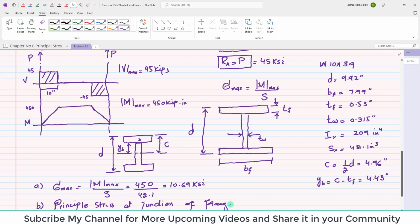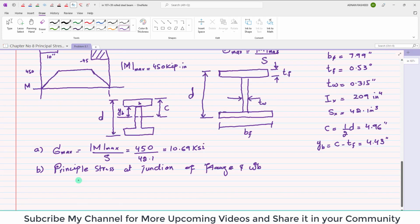For principal stresses, we know that sigma 1 or sigma 2 is equal to sigma average plus minus R, and R is equal to the square root of ((sigma x minus sigma y) divided by 2) whole squared plus tau xy squared.